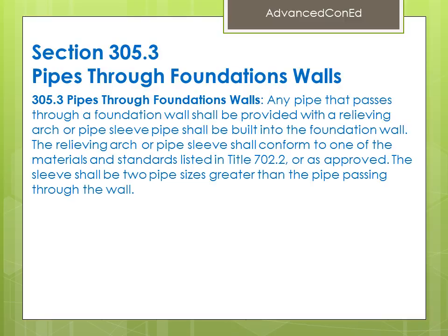Section 305.3, Pipes through foundation walls. 305.3, Pipes through foundation walls. Any pipe that passes through a foundation wall shall be provided with a relieving arch, or a pipe sleeve shall be built into the foundation wall.